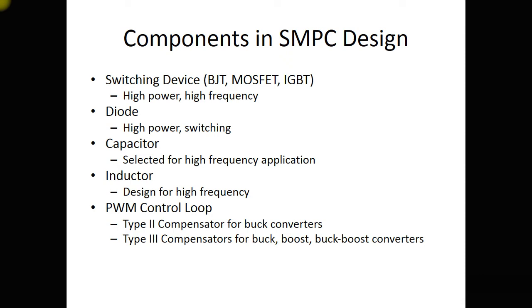Capacitor. This capacitor is a special type of capacitor suited for high frequency applications. Remember, our switching frequency is no longer a low frequency like power line frequency. It is to the extent of tens of kilohertz. Inductor, again designed for high frequency. And then we have the PWM control loop. This control loop involves what is called a compensator.